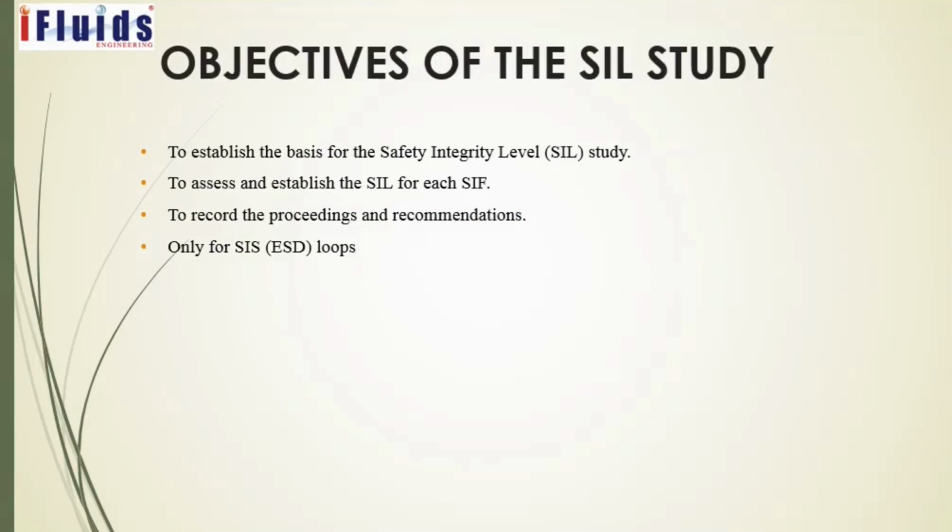Objectives of the SIL study: to establish the basis of the SIL study, and to assess and establish the SIL for each SIF. All this will be covered in detail in the following slides. The other objective is to record the proceedings and recommendations. SIL assessment and SIL study are the same, and it is only for the SIS, that's ESD loops.